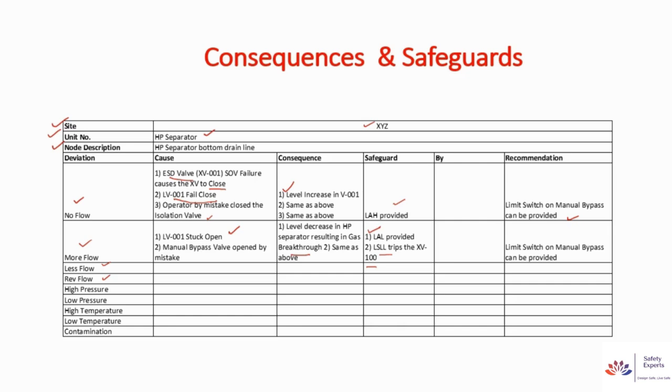So this is the way Hazop is normally performed, and this is how recommendations come up. Sometimes these recommendations are like, it must be followed, or sometimes like, it may be followed. So it is not very essential, but if it is followed, it is always better. It will always increase your safety and availability of the system. After all the recommendations are populated, some screening is done, and based on the Hazop team, the final recommendations are formulated.